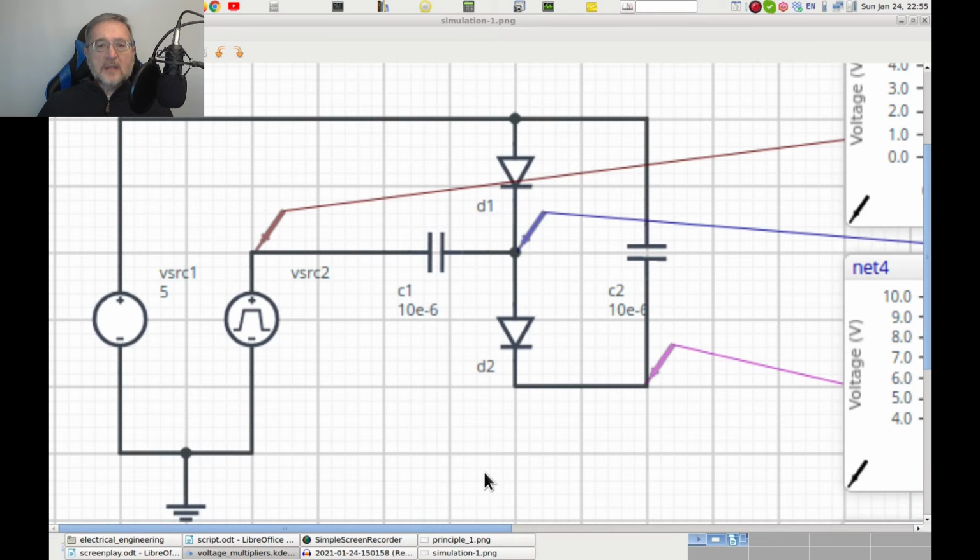To make it easy to understand what happens when we power up this circuit, I decided to run a simulation and obtain from it the diagrams of the voltage transients in the key points and at the output. Here is the circuit that I used for that. To be able to run the simulation, I had to find a way to automate the switch S1 while keeping a constant voltage on the upper end of D1 and C2.